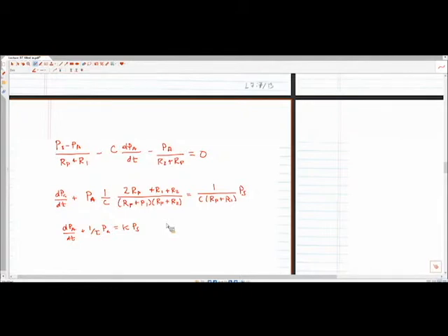Yes? How do we know that we wouldn't want to move over the 1 over C factor that's multiplied by the pressure source? You would want to bring that over to the rest of it. Is it because in standard form dP over dt has to be on its own? So when I say a standard form, sometimes you'll see the tau on the dPA/dt term, and sometimes you'll see 1 over tau on just the PA term. This is just getting it into one of the more standard forms and trying to get rid of a lot of these variables. It's a lot to look at, and I'm trying to make sure everyone can see that this is a first order differential equation. So I'm stripping away a lot of the variables and writing in terms of a time constant, which is, I hope, a little more familiar to a lot of people. So we could have had the coefficient on the dPA/dt as well.